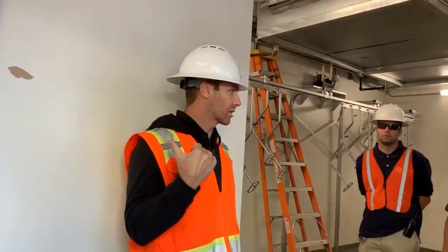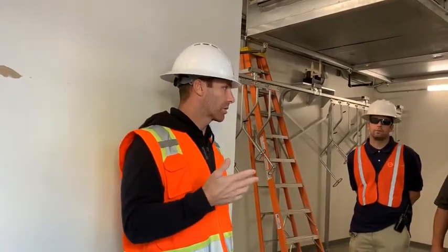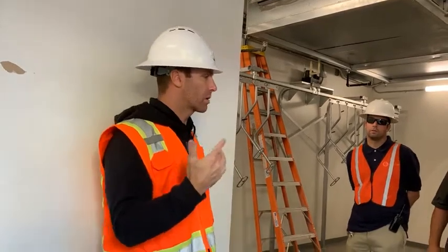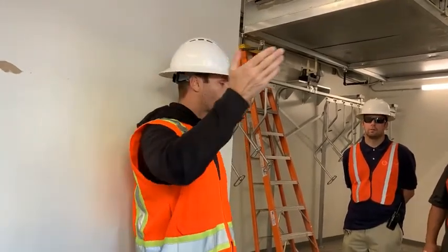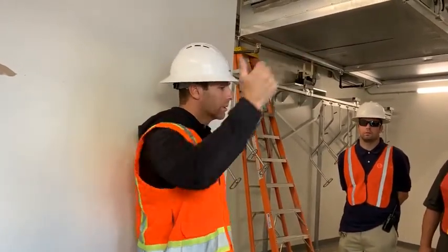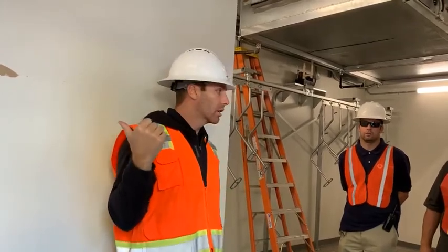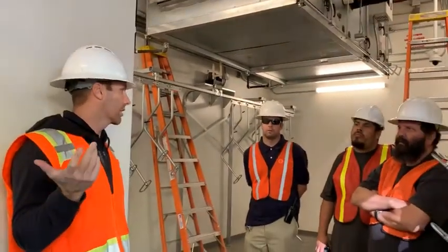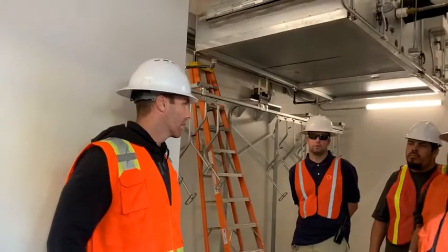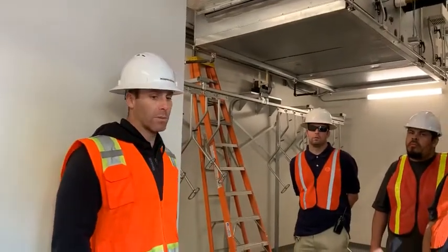One of the things with the exterior lighting, if it is on any type of time schedule or anything, if you're noticing the time schedule is not working correctly visibly, check that touch screen. Make sure that the time's accurate, the date's accurate, things of that nature. Okay? So that would be the first step if I would troubleshoot. So does the outside lighting come on a time schedule? Here, let me tell you right now. Sometimes it could have both.